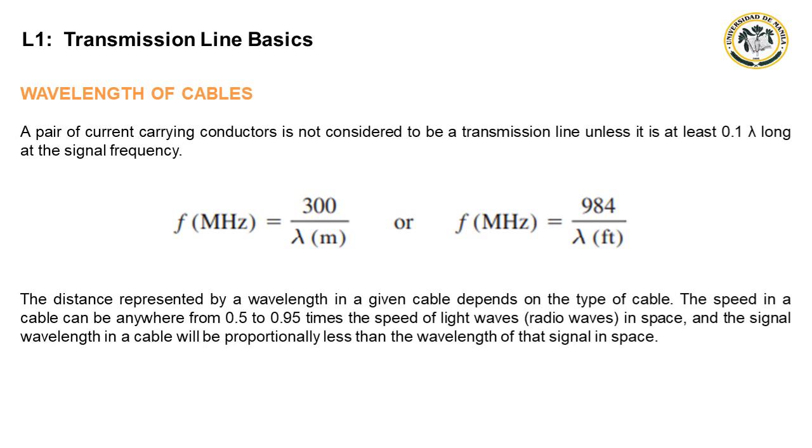Cables used to carry RF energy are not simply resistive conductors, but are complex equivalents of inductors, capacitors, and resistors. Furthermore, whenever the length of a transmission line is the same order of magnitude as or greater than the wavelength of the transmitted signal, the line takes on special characteristics and requires a more complex analysis.